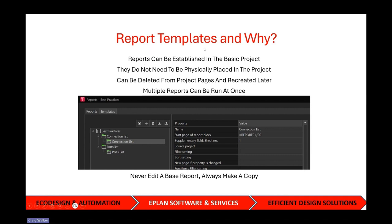Looking at reports, templates and why. There's two ways to generate reports. One is actually under this tab here under reports, and the other one is under templates. Now the difference is reports have to exist in your project. They have to have actual physical pages in your project. And the moment you delete the physical pages of your report, you lose your report.